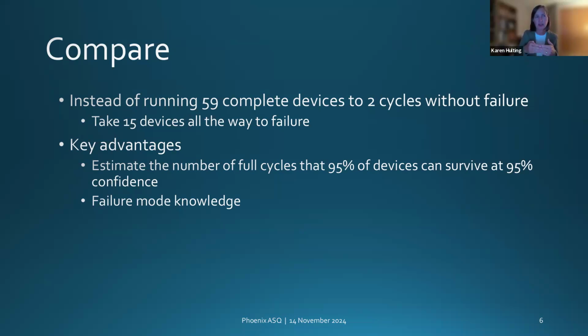It can be more difficult to get all the way to failure with a full device when it is, say, a capital equipment kind of device. In that case, what I would recommend is doing this cycles to failure testing component by component. In all cases, the more cycles to failure testing we can do, the better. But I've found that in every business I've worked in, there's a different situation for our trickiest demonstration test planning situations. So maybe in the question and answer, we can talk about more specifics on that.